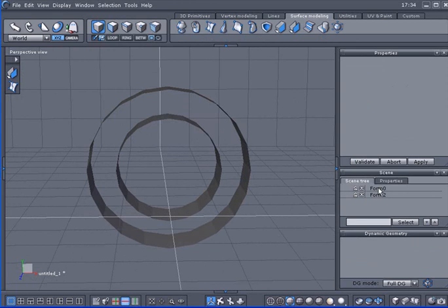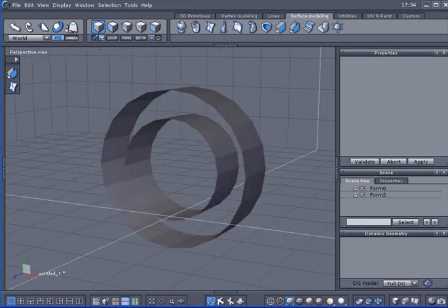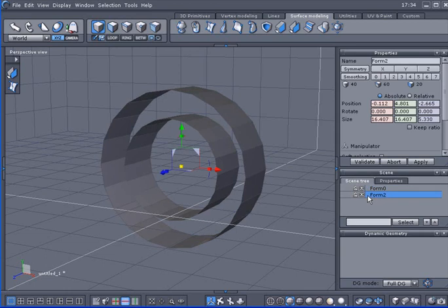And you can see I got them over here. Now here's a pretty good tip. I ran into this problem when I first started using Hexagon. When I'm over here trying to select something, as you can see, I'm clicking and nothing is happening. I could select the object out here, but if you move your cursor over to the left of the name, it'll select it. I don't know why that does that, but it's a lot easier if you just click them in here. Just follow where my cursor's at.